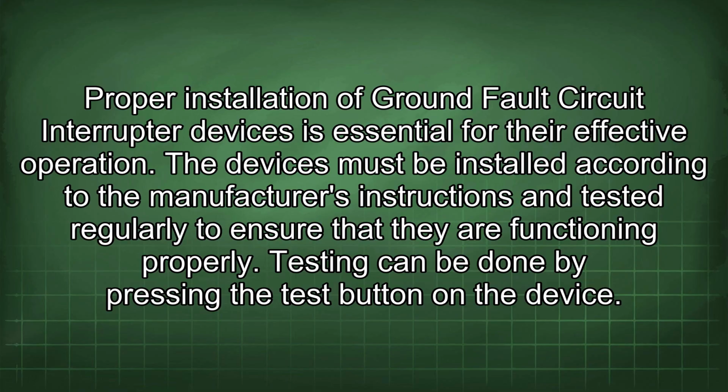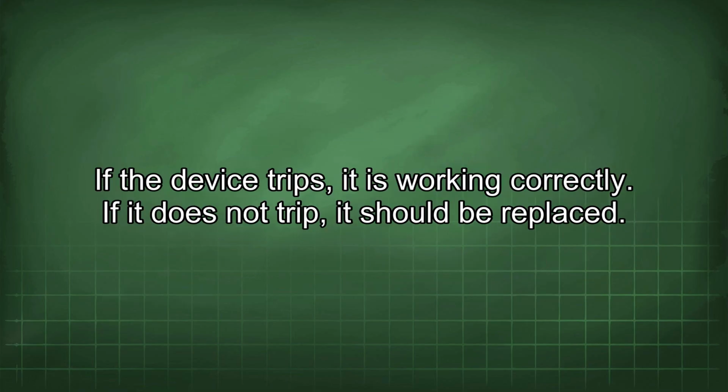The devices must be installed according to the manufacturer's instructions and tested regularly to ensure that they are functioning properly. Testing can be done by pressing the test button on the device. If the device trips, it is working correctly. If it does not trip, it should be replaced.